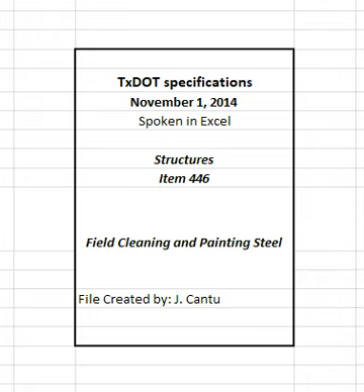4.7.3.3 Tape test. Perform the tape test, as necessary to determine cleanliness, on any surface before painting as follows. Press a strip of filament tape onto the surface by rubbing with moderate thumb pressure 4 times, leaving approximately 2 inches of one end of the tape free from the surface. Grasp the free end and remove the tape from the surface with a sharp pull. The surface will be considered to be contaminated and not adequately cleaned if visible particles cling to the tape.